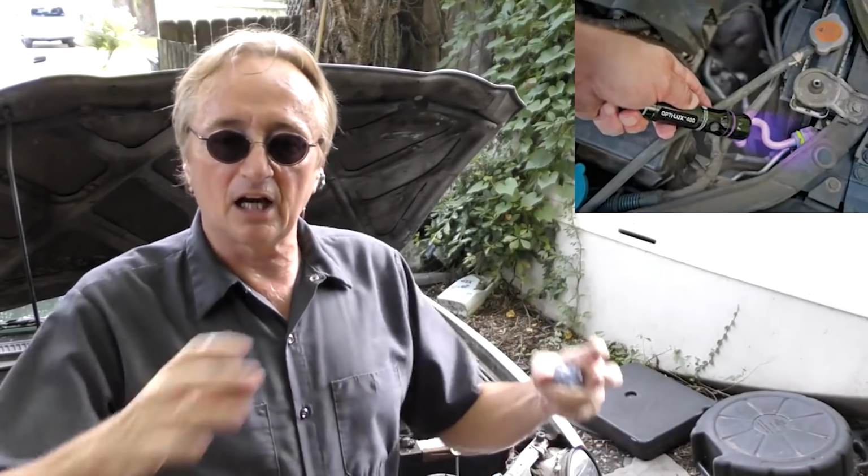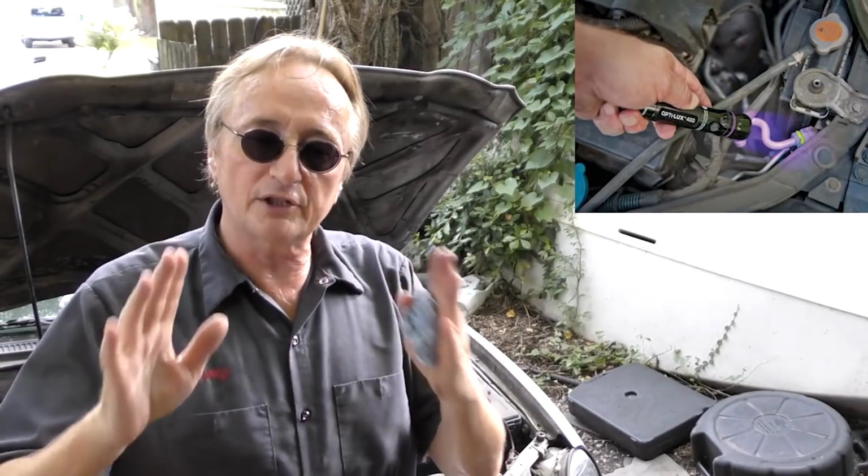And if you do add refrigerant, if your system doesn't have any of that leak dye, a lot of them are made with leak dye, but if it doesn't, you could add a little bit of the leak dye in too, so then when it finally leaks out, you'll see the dye coming out of the area and you'll know which one is leaking.